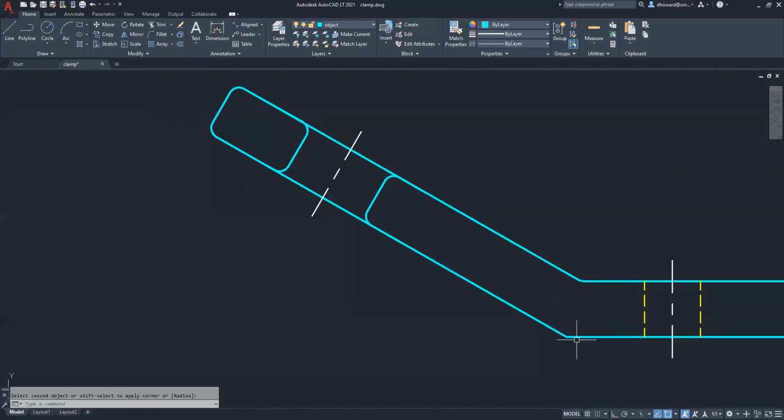What I was debating about is this bottom corner here. When I look at the drawing, it looks really square. The reason is, when I look closer at the drawing, I can see a little check mark on the bottom. I'll just draw it here. When you see a little check mark like this on a drawing, it's an old-fashioned indicator that this surface has been machined. So when it came out of the casting, it was probably rounded, but then it was machined flat, and that round got taken off. So that is why that corner is square looking, or sharp, I should say, in the drawing.